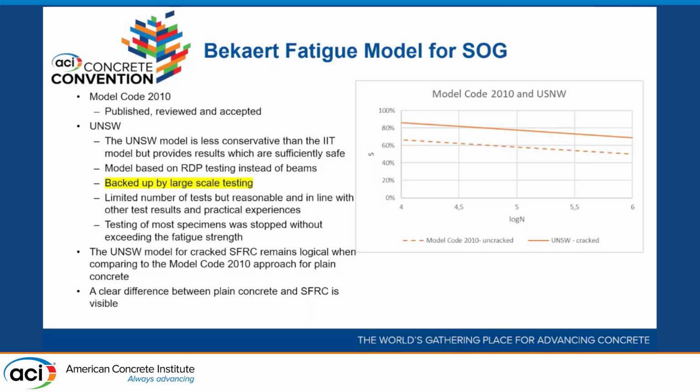So again, this is UNSW, backed up by large-scale testing. There's a limited number of tests. Obviously, there are practicalities with cost and time, but the results are reasonable and in line with practical experience, in line with what we expect. In all the testing in terms of cycles that we did, most specimens took the cycles without exceeding the fatigue strength. So very, very good performance out of the fiber concrete.